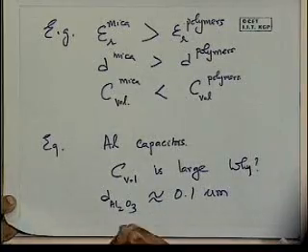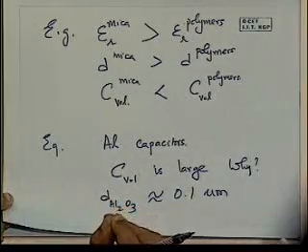But because of the very thinness of that layer, it is possible that you're going to have local breakdown. That's not exactly a very uniform layer. And then you're going to apply this field, and it's so thin that the fields are going to be very high across it, so local breakdown may occur. The beauty is that the electrolyte that is chosen is such that through some electrolytic reactions, it heals the breakdown. So where the Al2O3 layer, which is the dielectric, breaks down due to the high fields locally, the electrolyte heals that local breakdown by electrolytic reactions.